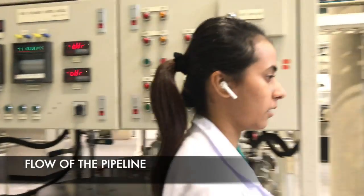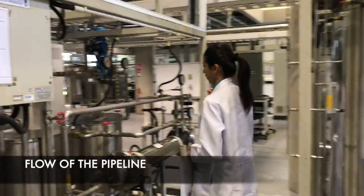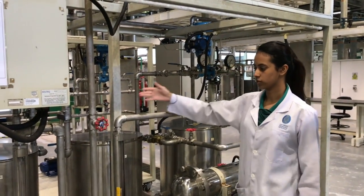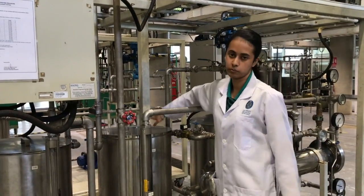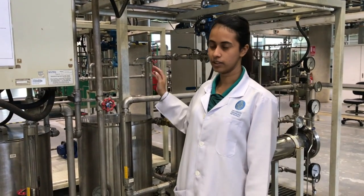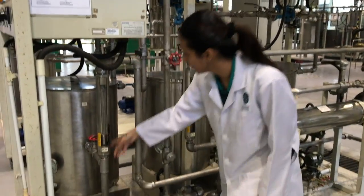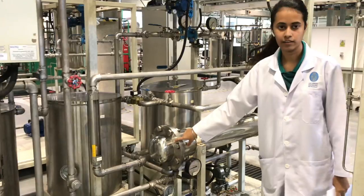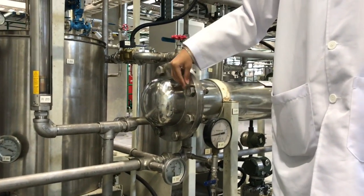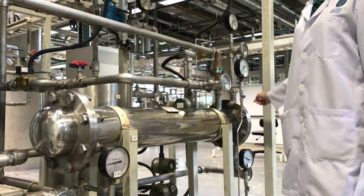And now I'll be talking about the flow of our experiment. So first of all, the hot water travels from the hot tank and the cold water travels from the cold tank, and this is the product tank where the cold water goes into after it has been heated up to its set point. So the cold water flows from here and enters the shell and tube heat exchanger. The cold water enters at the shell side and the hot water enters at the tube side.